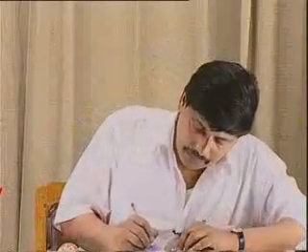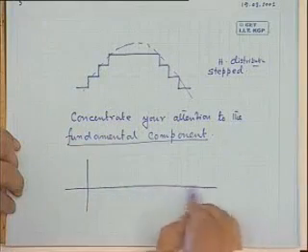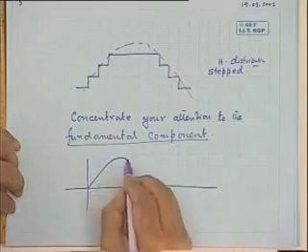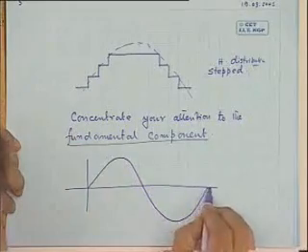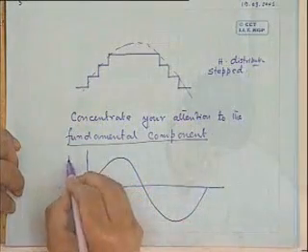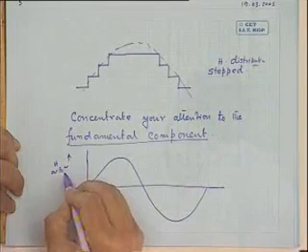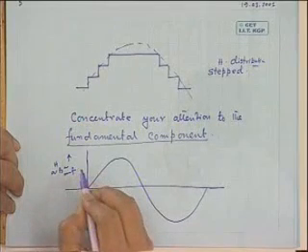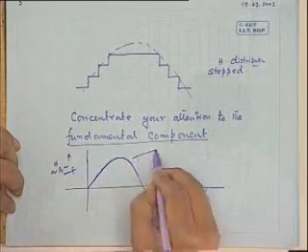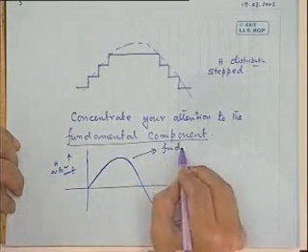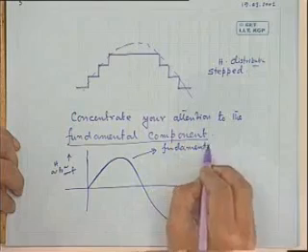Now, if I only concentrate on the fundamental, that means if a single coil is there, suppose a single coil, the MMF distribution is like this, or B distribution, or MMF, H or B or MMF, whatever you call. This distribution is like this, only the fundamental component.